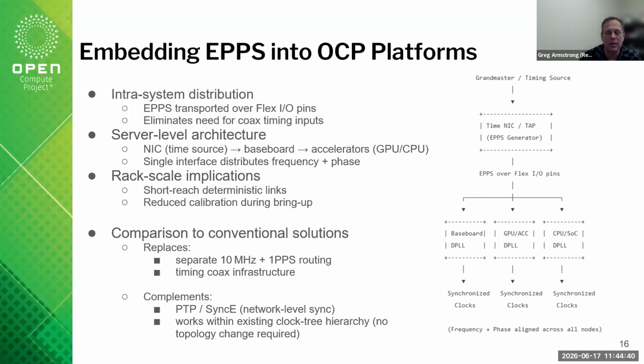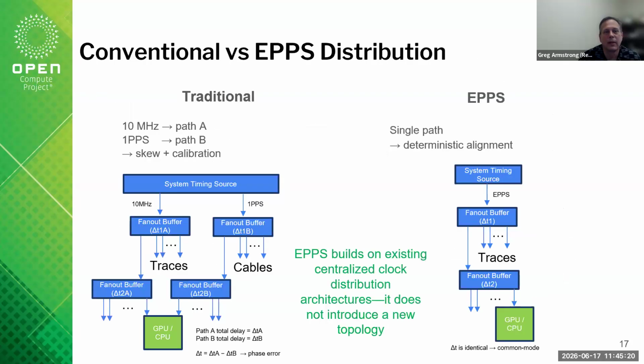But like I said, most even silicon phase lock loop technologies today have an integrated mechanism to measure clocks and even convert that to a digital representation of what's the phase difference if you want to do measurements. But it can also detect, right? It doesn't have to only look at rising edges. It can look at falling edges and tell you when did that occur, right? To aid in your own marker detection within it. When you see one cycle goes from 50 nanoseconds to 25 nanoseconds, that's a marker, and you can detect it using these time to digital converter techniques.